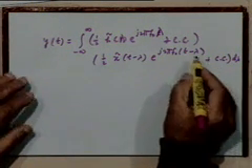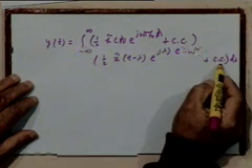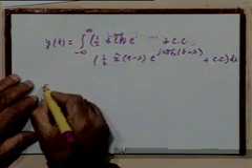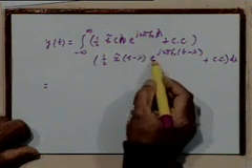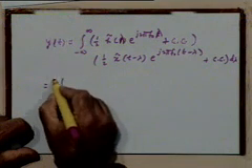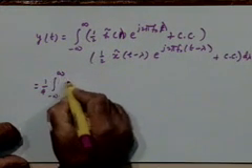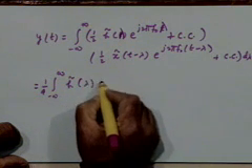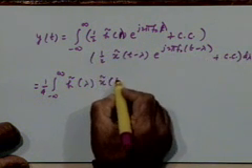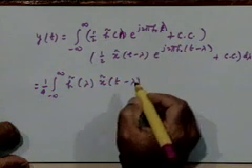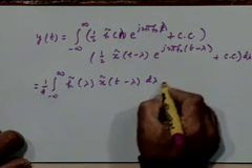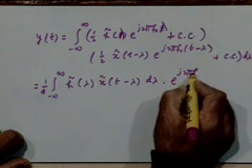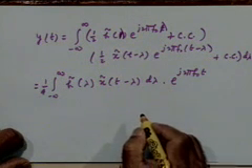Well, the complex conjugate also will contain half, so that's okay. Now if I proceed term by term, this is lambda here, right? What will be the product of the first two terms? This will be 1 by 4 h tilde lambda x tilde t minus lambda, and what happens to the product of these two exponentials? It is e to the power j 2 pi f naught t, because the lambda term will cancel off, right?